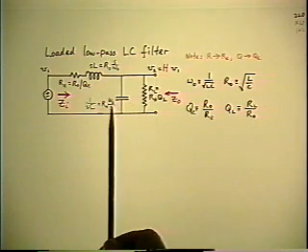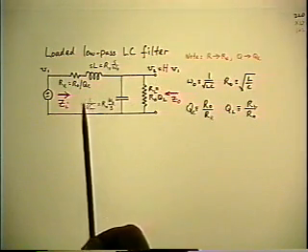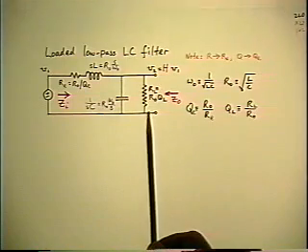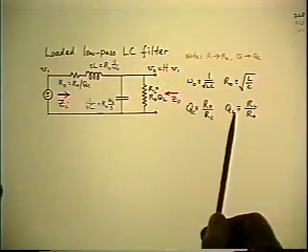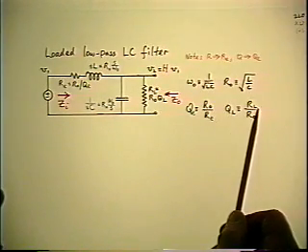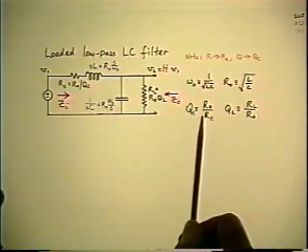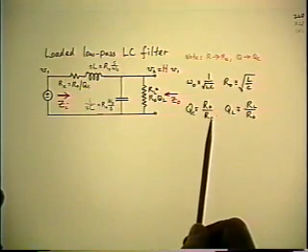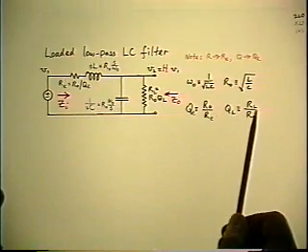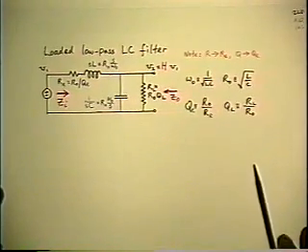Okay, now we've got normalized quantities in place of the original circuit elements, but we have a new circuit element. So it's to be expected that we could benefit from defining a new normalized quantity. Let's call it a Q factor. So let's call it a QL corresponding to the RL. So here's the definition of the QL. Now you notice it's defined upside down from the first Q. In other words, the RE is in the denominator in the first case. It's in the numerator of the second case.